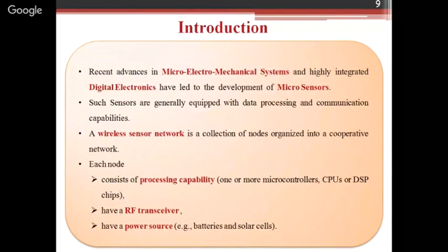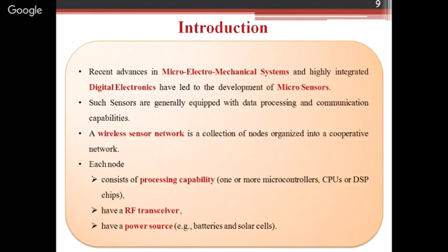And because we are talking about a huge network here, all the sensor nodes are organized in a network, and they are going to perform one specific application-specific task. So that data which they have sensed and processed, they have to communicate to their neighbor nodes. Okay, and the most important thing, a lot of power is consumed when data is communicated. Once the sensor node has to process that data, it has to apply all the mathematical operations onto it, and then send that data to its neighboring node, so that finally the data can be transmitted to the base station, where it can be decompressed.